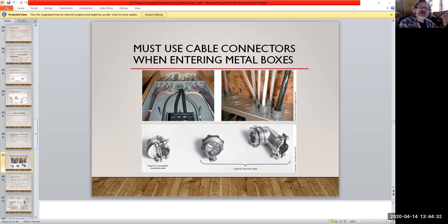And then on the other side, when it comes in the panel, notice, nice and clean. You really want a minimal amount of sheathing, so you want to peel that sheathing back pretty much to the edge of that connector, or as close to it as you can, and then, of course, keep the sheathing on the outside. And yeah, you can run into different ones. They even have so many weird looking ones, but these are the typicals.